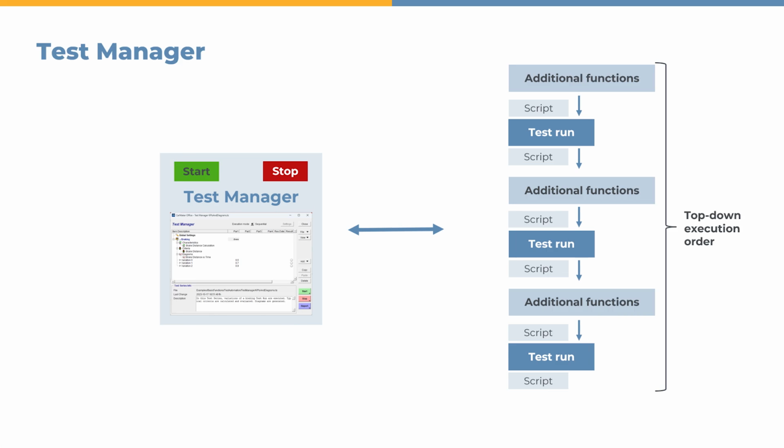Now let us look into one of the other methods provided by CarMaker to assist test automation. The test manager is a supervisor, which supports the user with an overview of multiple test simulations. The file saved in the test manager is called a test series and is postfixed by .ts. A test series in a test manager basically consists of a set of test runs that are executed automatically. However, a test manager offers a lot of functionalities to optimize the preparation, execution, and analysis of test runs.